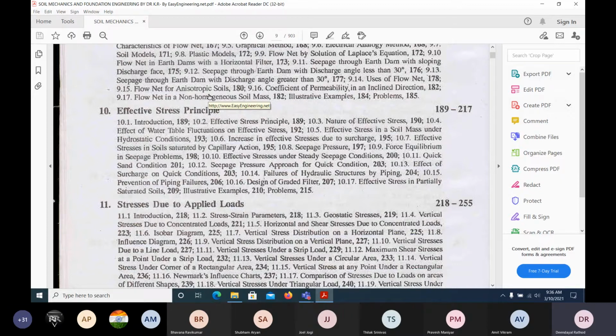But you should remember that the total stress, you can say, is whatever stress you feel at the bottom, okay, with the depth h, equal to gamma into h, where gamma can be saturated unit weight, okay. If you deduct pore water pressure from that, it will give the effective stress, okay. And this effective stress is very, very important for our construction, okay.